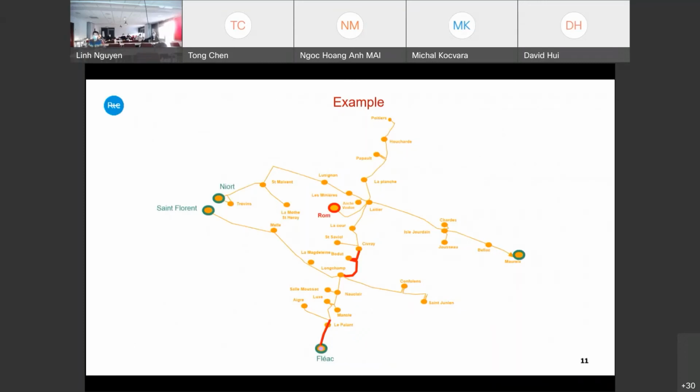So here behind these nodes, which are transmission nodes, there is a distribution grid, which is operated as a tree, but physically it's meshed. They open some bus bar coupler somewhere, so it's operated as a tree, but they may close it if there is a fault somewhere. They can switch on something, and then the tree will be changed. But these are not real-time operations. And second, in this area, maybe there is a wind farm here. They can move it to the next location, but basically everywhere here is overloaded.